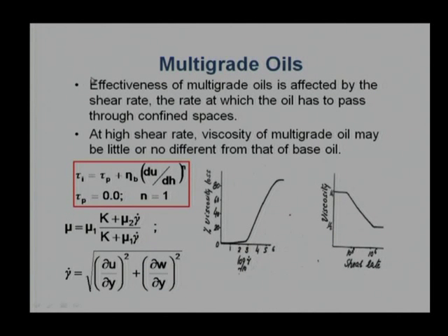Even if I use the multigrade oil 10W40, in one case K turned out to be 20,000, and in another case, for the same specification, K turned out to be 50,000. In that situation we say the K equal to 50,000 will be the preferable multigrade oil compared to the K value of 20,000. So, based on this shear stability parameter, we can choose multigrade oil. Otherwise, for the specification, both oils will be 10W40 and we will not be able to distinguish much. From one company to another, the distinction can come using the shear stability parameter.